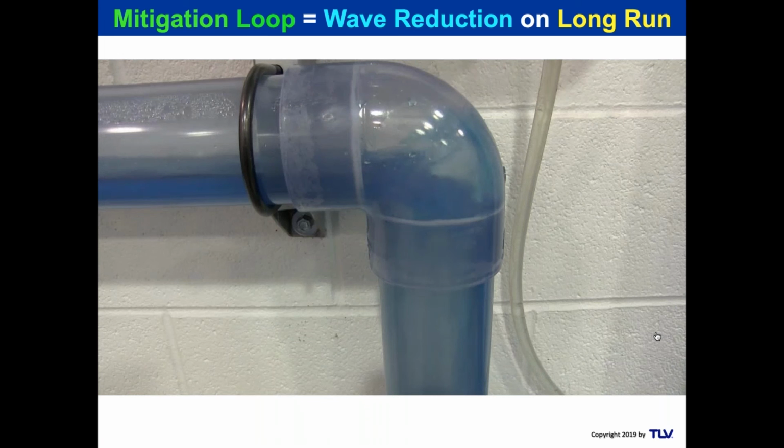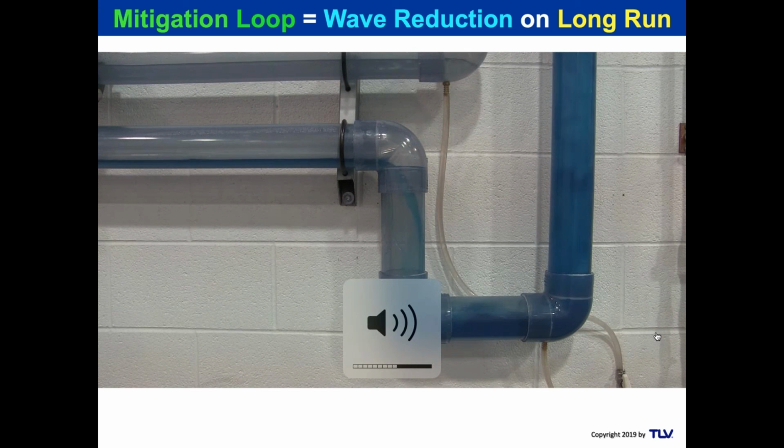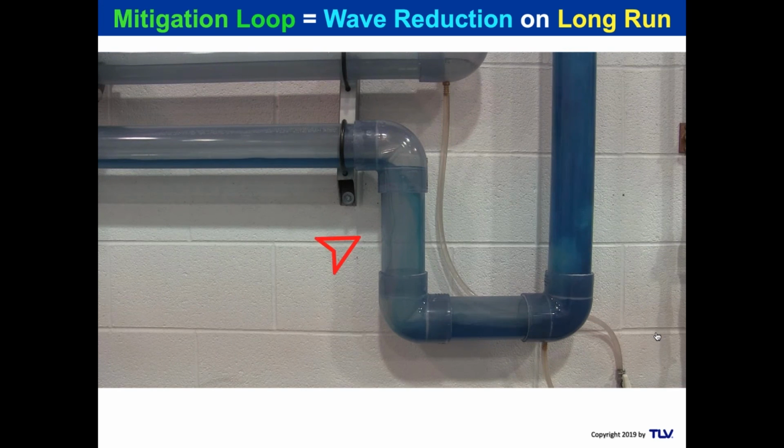And let's take a closer look at the elbow. Again, it would be a long radius elbow. You're not getting the same hammer effect that you had before. And let's go down to the interface, and you can see why this should be long radius elbows when you take a look at the interface. You see a lot of action at the interface, which is why you want an engineer experienced in fluid dynamics and stress analysis to be able to make sure that that part of it is designed properly. You don't want to have any problem there where that arrow's pointing.